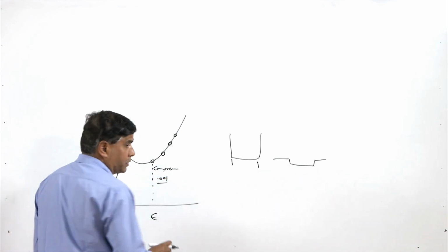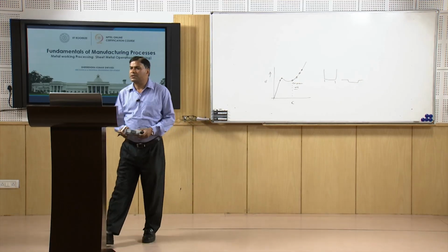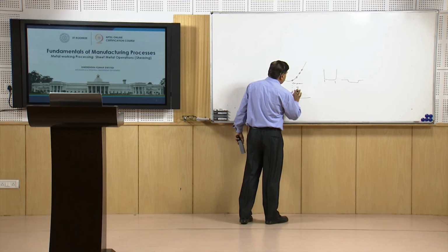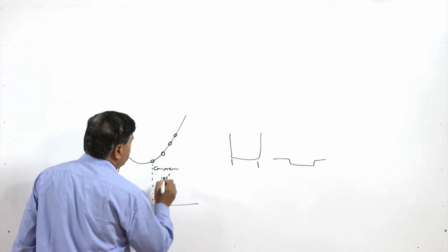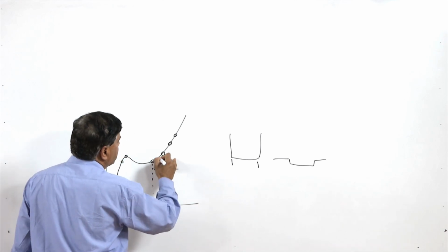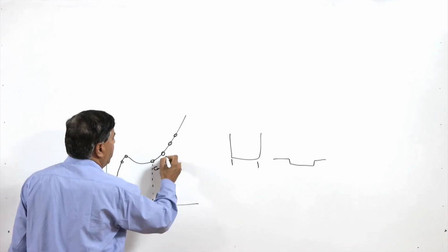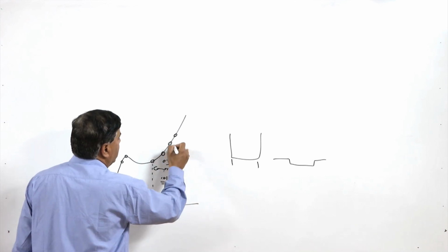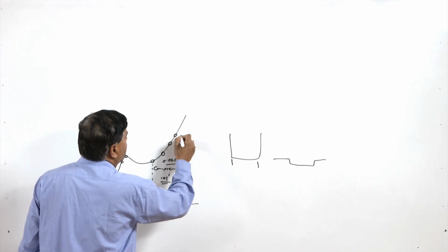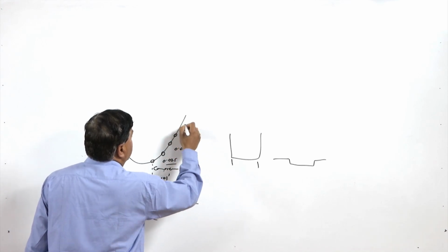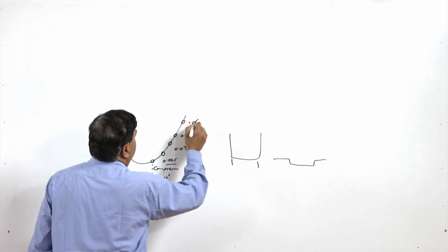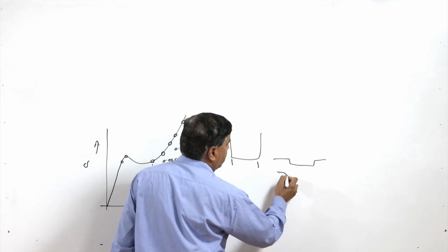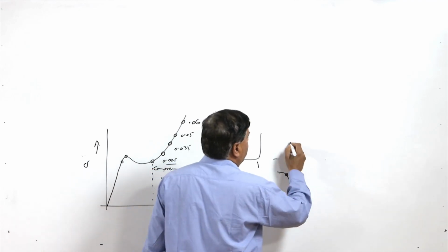Say this is equal to 0.01 inch. So, for the smaller magnitude of initial entry, causing a depth of 0.01 inch, when the depth increases, obviously the compressive strain and stresses will keep on increasing. So, they will cause more compressive strain, and after reaching a particular value, say 0.05, we will find that the crack nucleation will start from both sides, from the lower side as well as from the upper side like this.